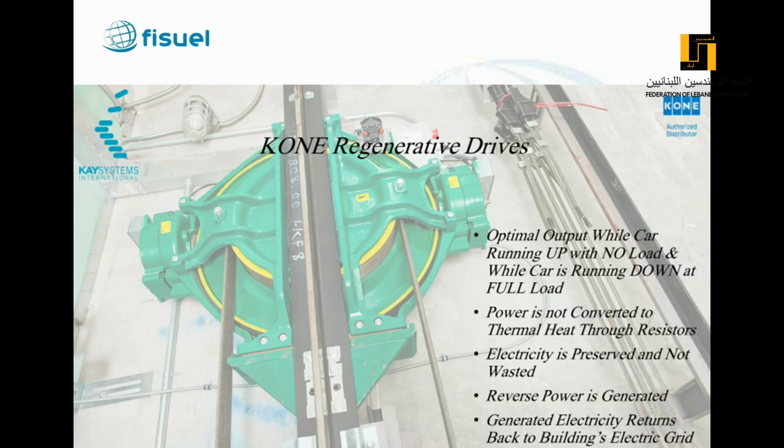In addition, anytime the elevator slows down, energy is created and captured by the regenerative drive. The KONE drive uses modulated line bridge technology, and hence, when the KONE EcoDisc motor acts as a generator, the braking system generates clean power with low harmonic distortions, making it convenient to be linked back to the building electrical network that can be used elsewhere in the building or drive another elevator. Simple simulation and approach that further explain the regenerative drive concepts.